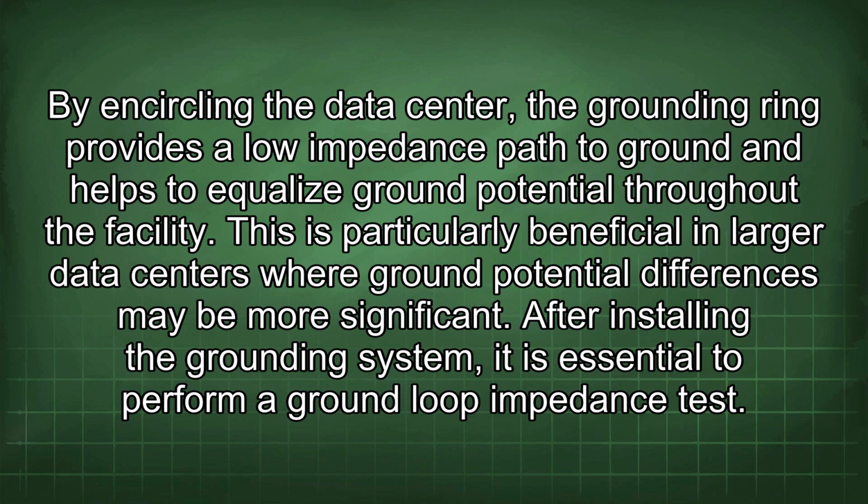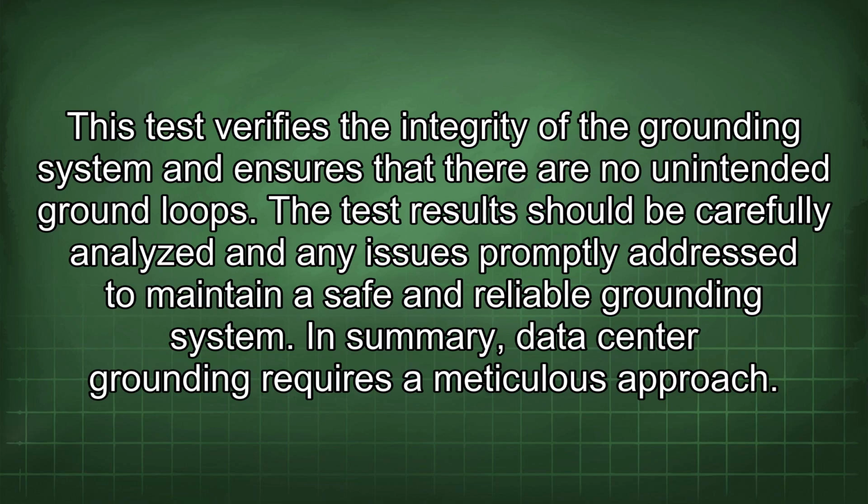After installing the grounding system, it is essential to perform a ground loop impedance test. This test verifies the integrity of the grounding system and ensures that there are no unintended ground loops. The test results should be carefully analyzed and any issues promptly addressed to maintain a safe and reliable grounding system.